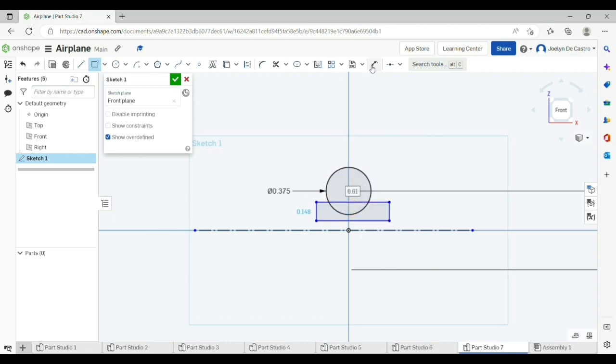Right-click at the end of the rectangle command. Now use the dimension tool, and take the bottom edge of this rectangle to the center line. Click on that. This makes the size of the center hole, which is 0.25. Then from the top edge of this rectangle to the center line, pull down below. Set the overall height of 0.45.